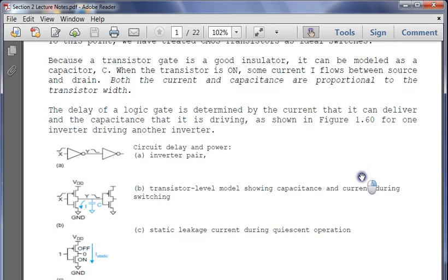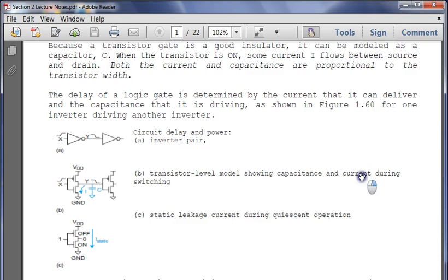So the first thing we talk about is just delay. Phase doesn't happen instantaneously. We talked about these perfect switches. Here I kind of alluded to this before: we had this idea of a buffer. A buffer is just two inverters put back to back. The reason we want to use a buffer is for timing. Let's say we have multiple signals, and one of them is 10 nanoseconds ahead of the other. We can insert a buffer to make this signal wait so that they come on at the exact same time.